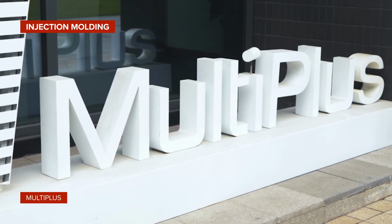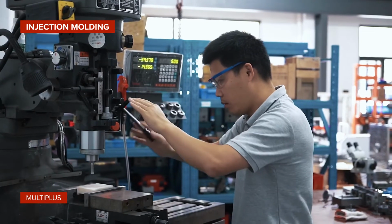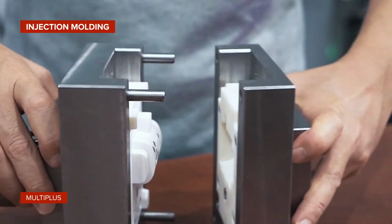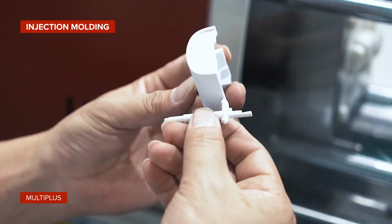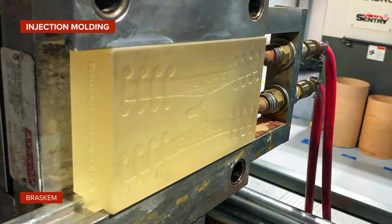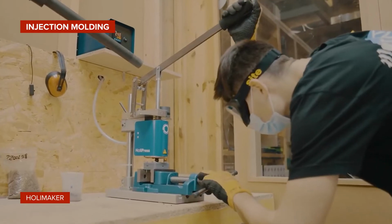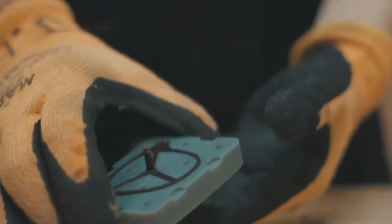Shenzhen-based contract manufacturer Multiplus uses 3D printed injection molds with the strong, stiff, and heat-resistant Rigid 10K Resin on Form 3 SLA 3D printers, shortening lead times for small batches of around 100 injection molded parts from 4 weeks to only 3 days. Additional examples include emergency mask straps by petrochemical company Braskem, and prototype and pre-production parts for the clients of manual injection molding machine manufacturer Holimaker.